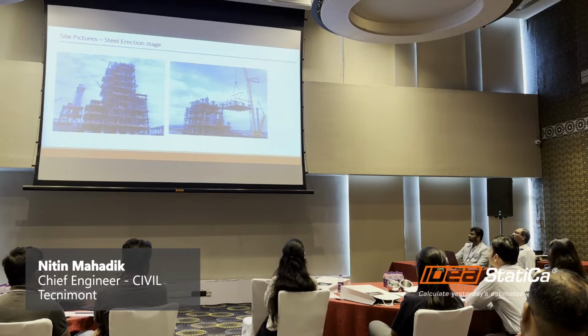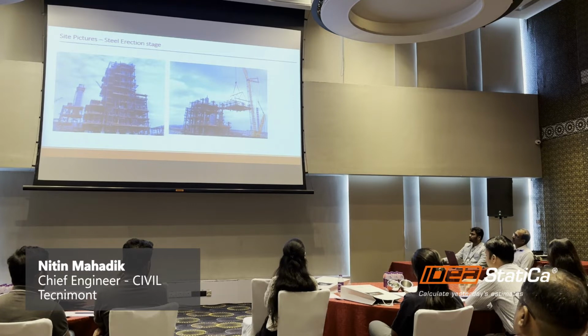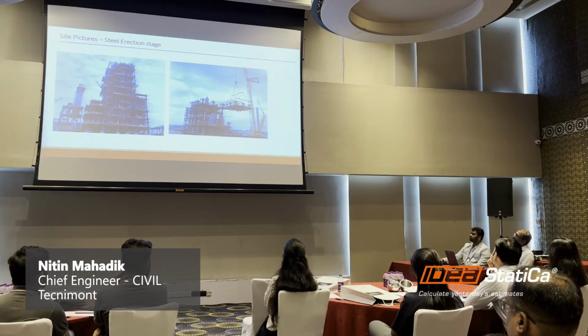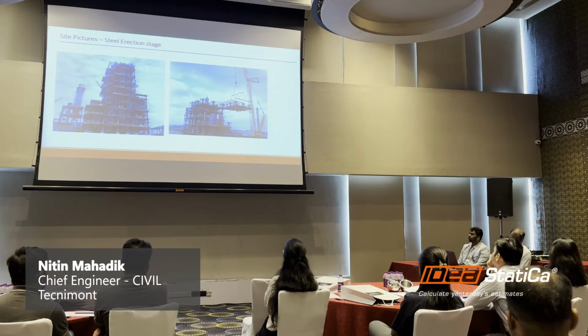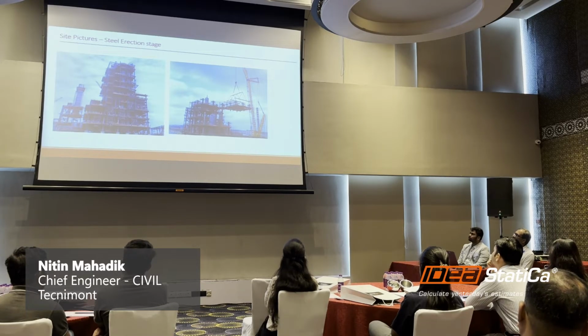So the splices that we found, there are many issues which we need to address, and at that time IDEA StatiCa rescues us, you can say. The butt splices we use for columns facilitate the erection. At the same time, the lifting lugs, I will show you in the next slide, are designed. All the connections have been designed in IDEA StatiCa using their Checkbot, because the whole structure is designed in SAP2000 for the global analysis, and using the Checkbot facility in IDEA StatiCa, the forces are transmitted to IDEA StatiCa to analyze and design the connections.